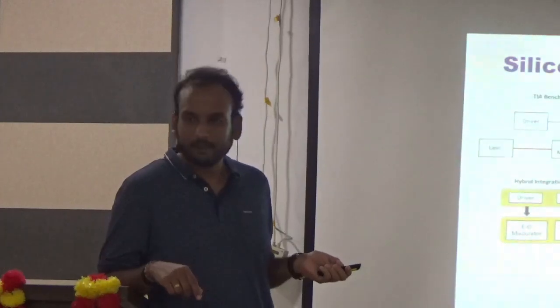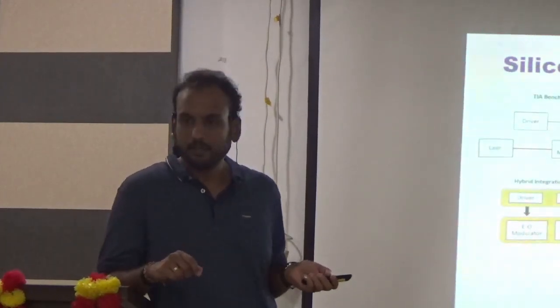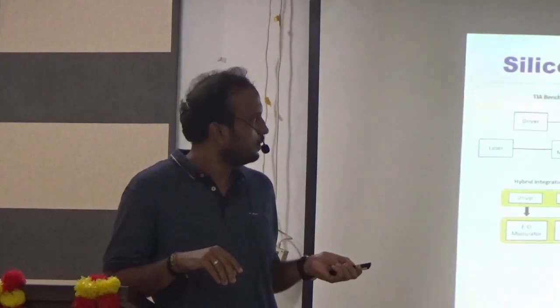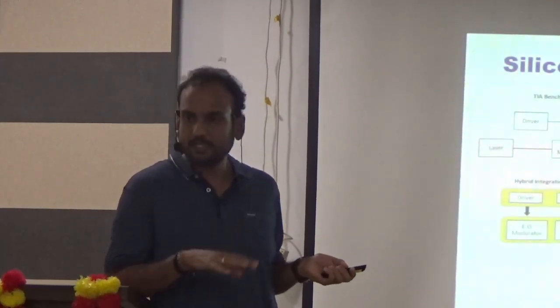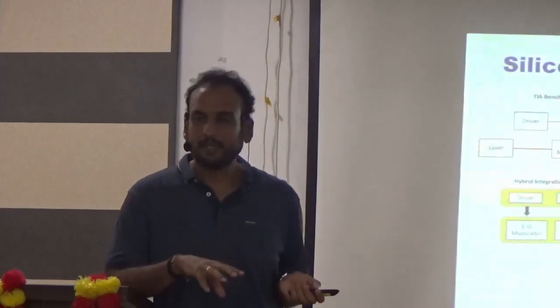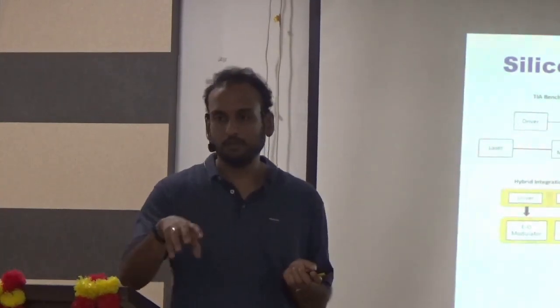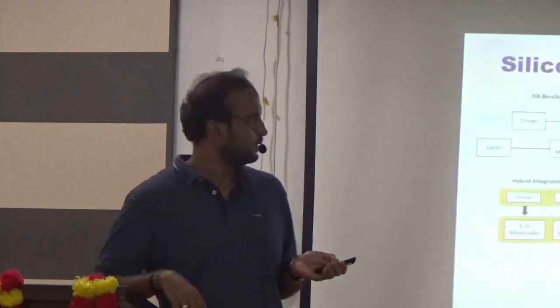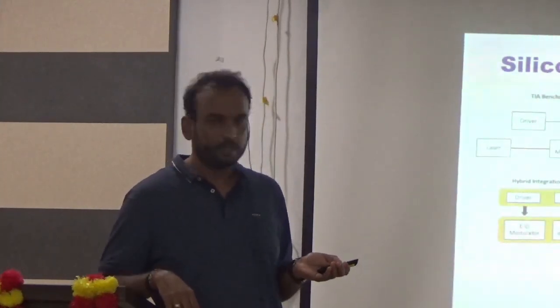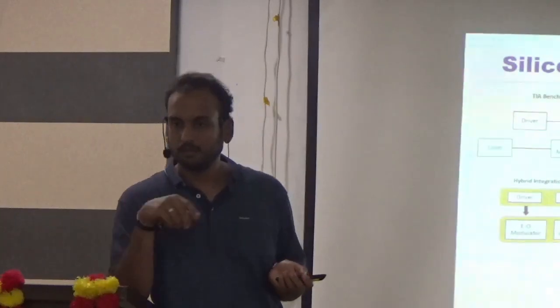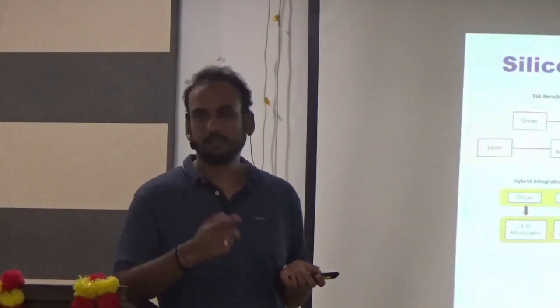If you have higher capacitance, you will get lower bandwidth. So that is the main idea. If you want more bandwidth, you try to reduce this capacitance. I will discuss this capacitance; there are a lot of contributions from different components. This is just a model. It can come from the amplifier or maybe the device.